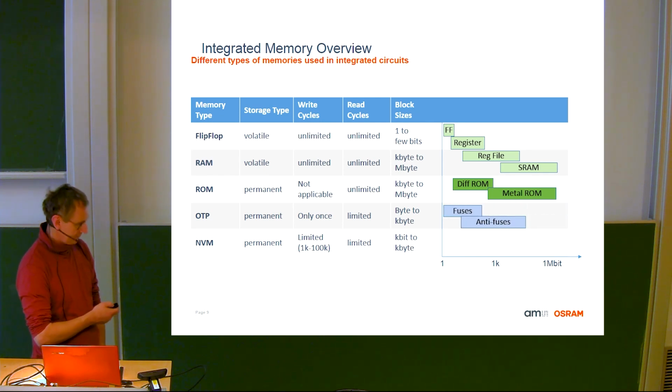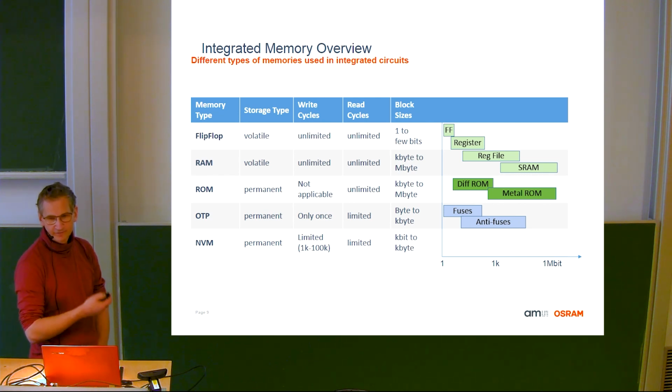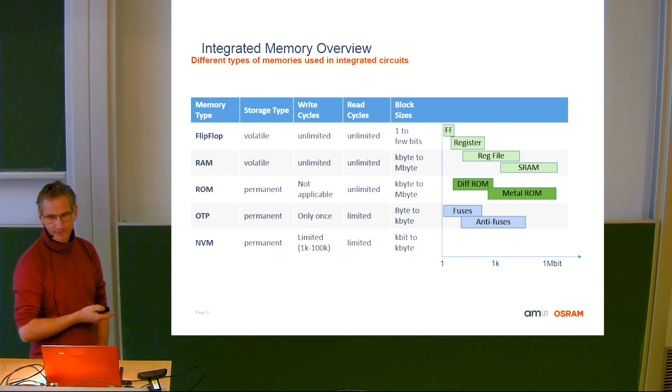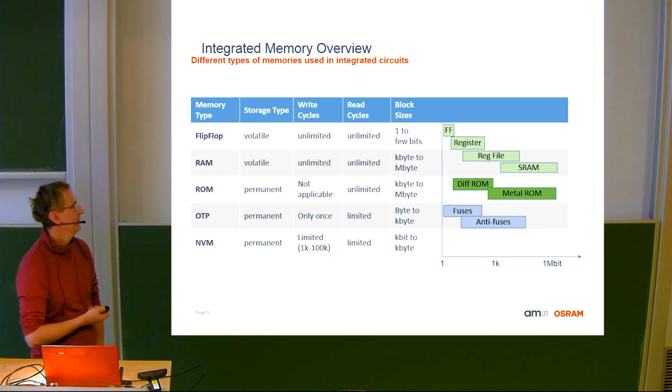And then on OTP, you can start trying to use elements, and we distinguish here between fuses and anti-fuses. A fuse is more or less like what you have with your electricity at home. If you remember what a fuse is, it could cut your power line for some reason, typically for a high power event. So typically it's connected, and at a certain event it's not connected. So it's open, and with this information you can build a 0 or 1 into a memory.